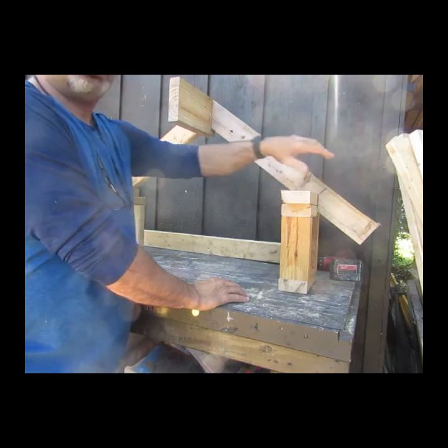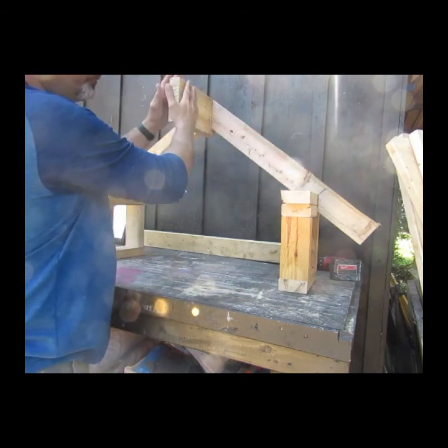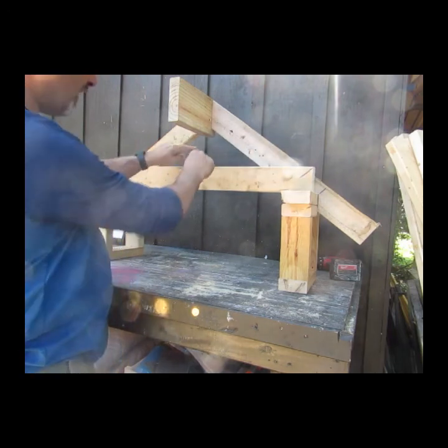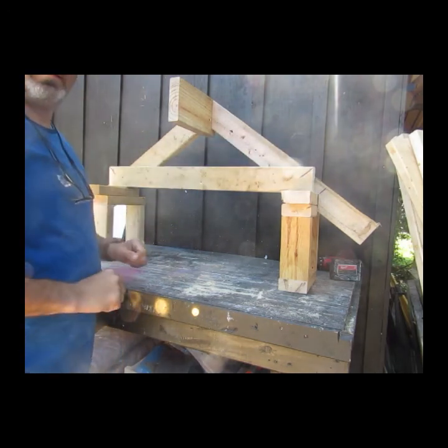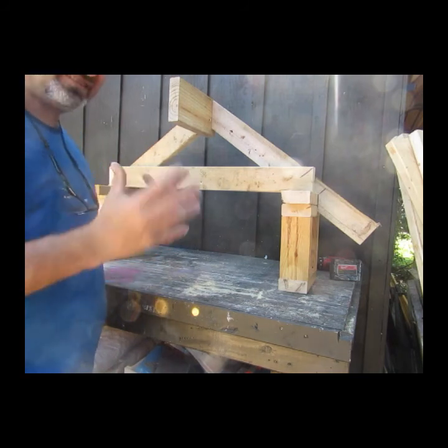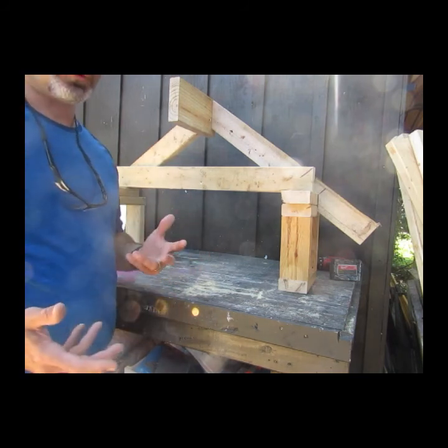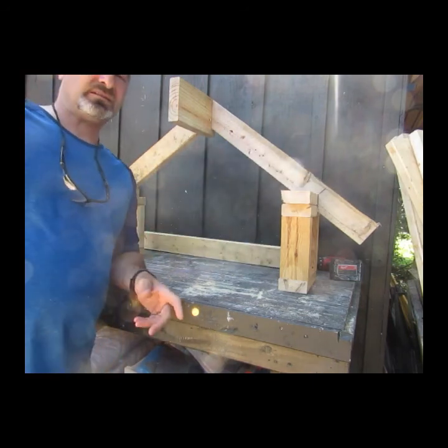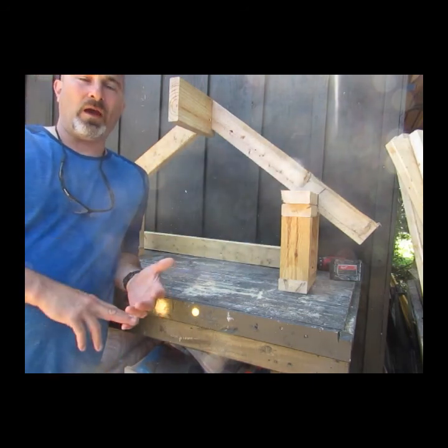The rafter, the ridge beam, the bird's mouth, the rafter tie, and if it was much, much bigger, you'd have a collar tie up here. That is all put together, the whole system working together. That's what keeps your structure from falling down. So every little piece counts, and understanding each piece counts in order to put it together in the right way.